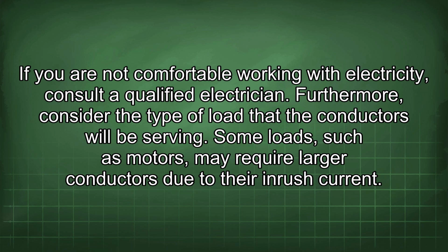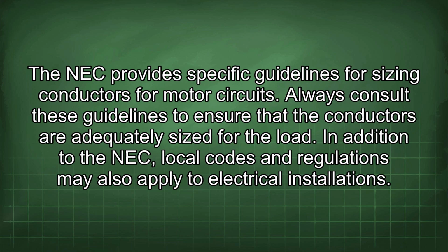Furthermore, consider the type of load that the conductors will be serving. Some loads, such as motors, may require larger conductors due to their inrush current. The NEC provides specific guidelines for sizing conductors for motor circuits. Always consult these guidelines to ensure that the conductors are adequately sized for the load.